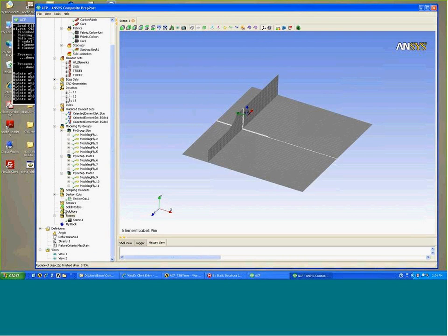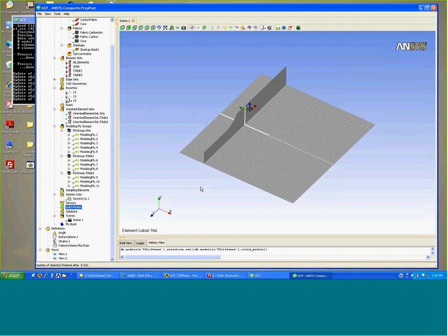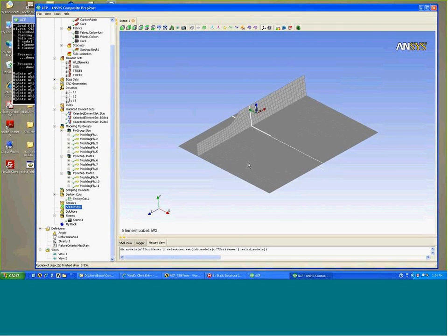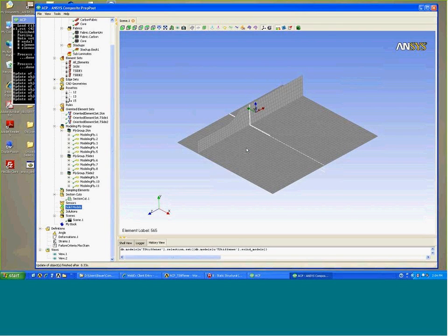including new ply definition in describing our new model. For solid models, this allows you to take an existing ply definition and mesh definition and extrude that in a various number of ways. This is a very powerful feature for extruding shell and ply definition into solid finite elements and layered solids, essentially. Let me get you started with showing you in this example how to generate a solid model.